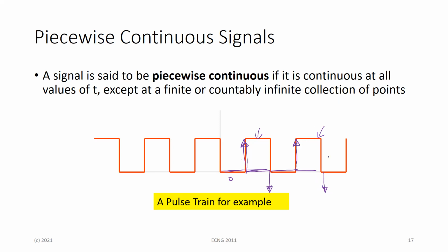Impulses mean that whatever it is is going to try to go to its maximum value in a limited period of time. So if this is a motor, then the motor is going to suddenly try to accelerate to its maximum speed. And then a very short time later, you get an impulse trying to stop the motor by giving it a reverse voltage in the opposite direction. So that's the consequence of having to deal with piecewise continuous signals.